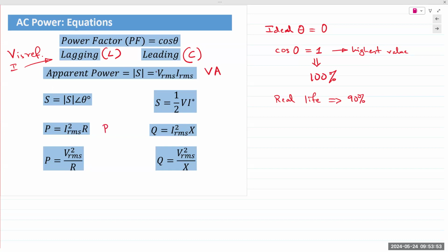These equations come from a combination of Ohm's law and the standard power equation: V equals IR and P equals IV. Chapter 1, if you'll remember, I stated this. This was in the first week of class, so it's probably a distant memory. But same standard form, no difference. Apparent power is the product of the voltage and current, but it's the RMS values, V RMS times I RMS.